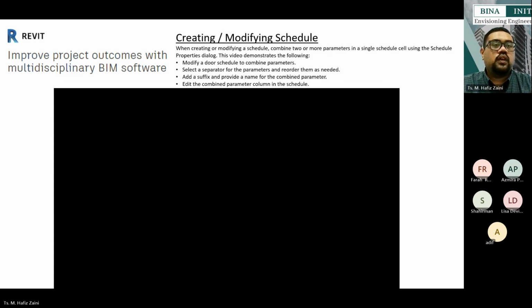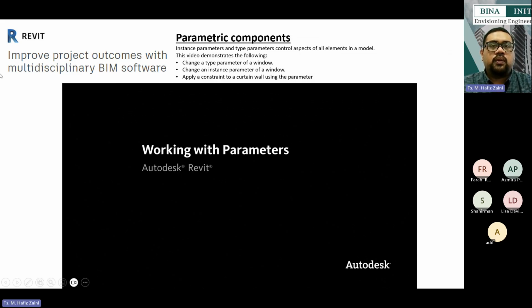Okay, the schedule is one of the benefits that comes from this tool. It will benefit the 5D quantification. For 5D, the ideal process involves another tool. Okay, in the market they have a few, like cost apps and Cloudon software, from which you can do the extraction of quantity. But from Revit you can also do the quantification by extracting the schedule of quantity, and you can also put it in the 2D drawing. Okay, so this is what we call the parametric component.